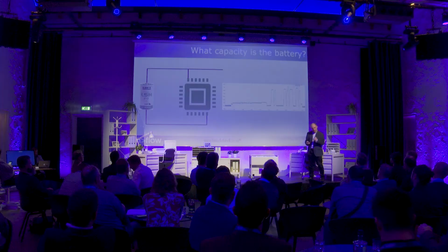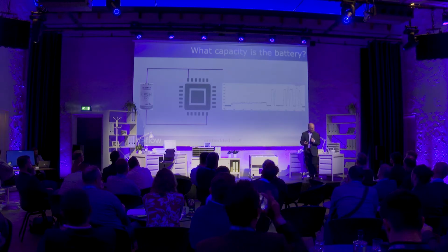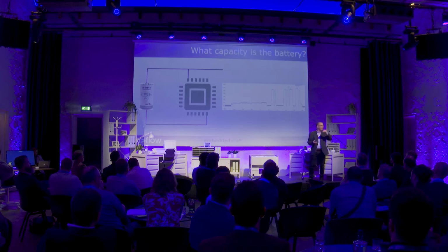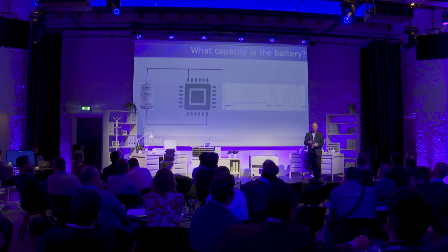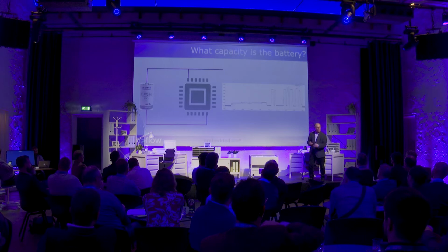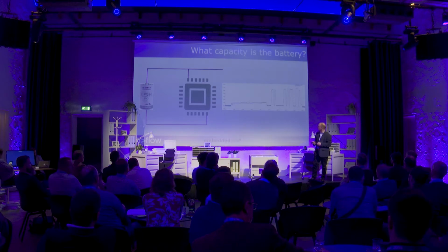Okay. So we have to scale the battery, and we have to understand what the microcontroller is doing and its low power modes. And a convenient way to do this is to profile how much current the microcontroller will be taking at different times. Hopefully it's in an ultra low power stop mode for most of its life. But we're going to need to know what the manufacturer of the chip will claim for that ultra low power stop mode.